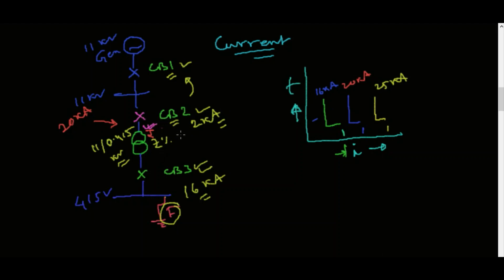If the fault location is far from the source, or there is considerable impedance in between the two protective devices, then this coordination will work fine. For this transformer, there is the transformer impedance, so it will restrict the fault.